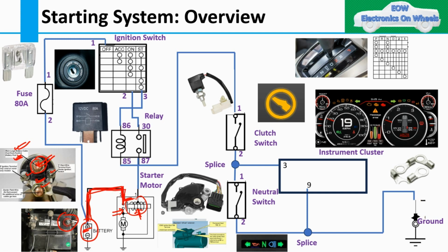That is the first thing. Second, this particular terminal we never use and never disassemble, we don't touch it. Then you might have seen one connection from the solenoid to the terminal, that is an internal connection. Then there is one S start wire terminal from the start ignition switch.